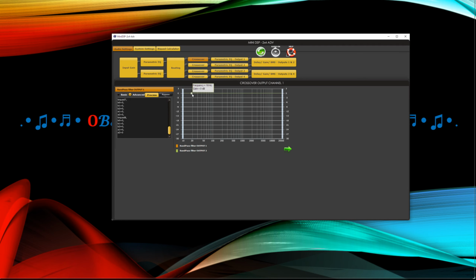As you see, there is only a thin green line here at 0 showing the frequency response because there is no change in frequency, but the phase response is corrected as required at the end of this correction. And then you upload it to miniDSP by clicking this button. That is all for the biquad calculation and entering into miniDSP.